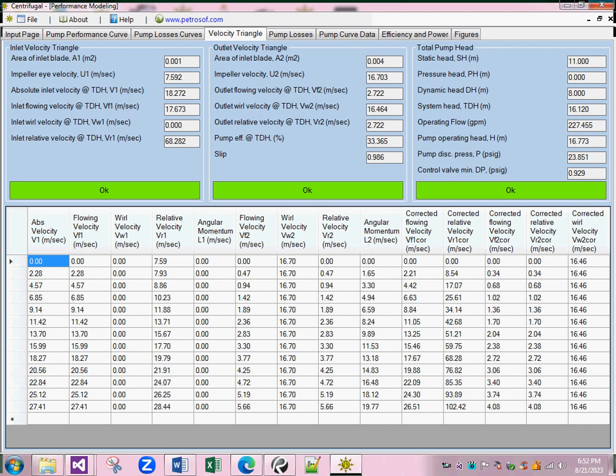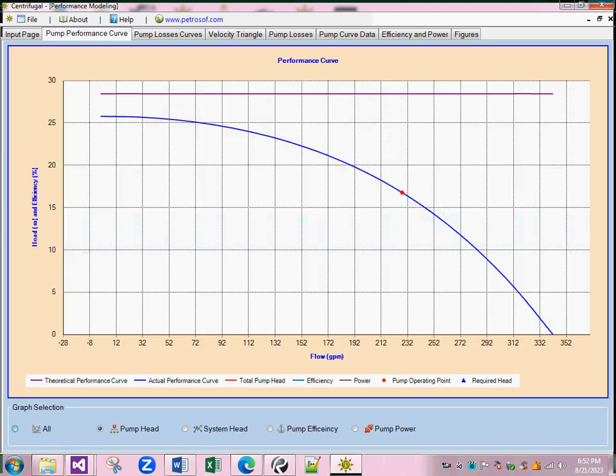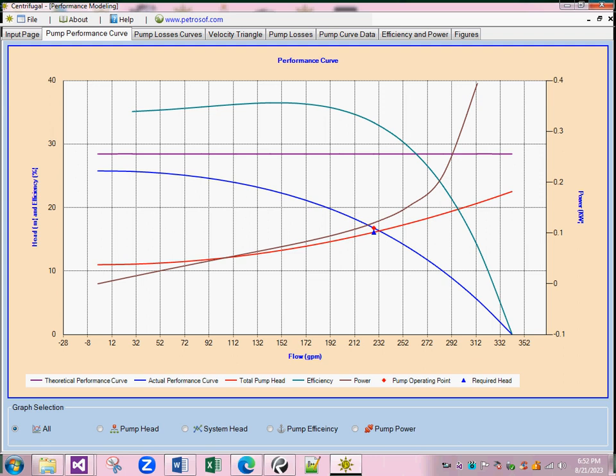So it is always better to have some margin over here, which means that the pump is actually capable of producing a head greater than the required head where the pump is supposed to be working, so that we should always have a control valve or some kind of a pressure drop valve at the discharge line of the pump to compensate for that difference.